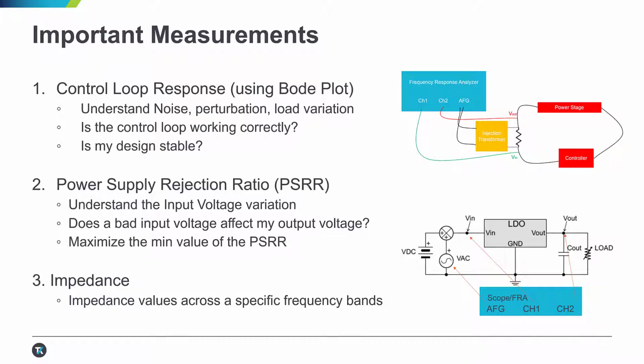So impedance usually is done with a vector network analyzer, or it's most commonly developed through network analyzers. However, there's a couple of measurements that really preclude using a VNA for PDN type of impedance responses. One part is VNAs are usually very good at measuring high frequency response, say across different cables or PCB traces. However, they usually don't do very well at measuring low frequencies or measuring very low impedance values.